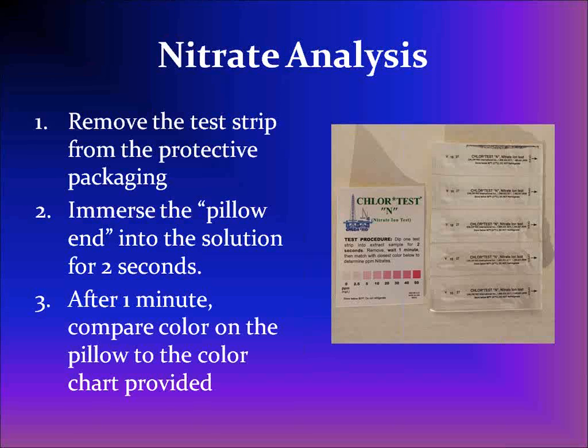If the specification requires you to measure the nitrate ion concentration, you can use the same sample that you use to test for chloride. Again, just use a different indicator strip.